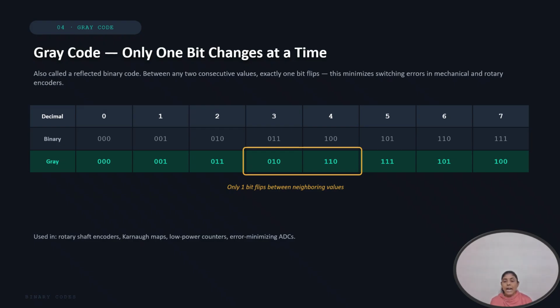I will take 5 as an example. What is the value for 5? 101. How are you getting that 101? Because of that 4 2 1 code. What I said, the MSB should be taken as such. So what is the MSB there in your 5? 1. Next, the MSB should be XORed with your next value. What is your MSB value? 1. What is your next value? 0. So what is 1 XOR 0? The value is 1.